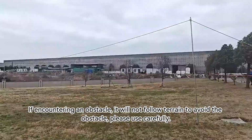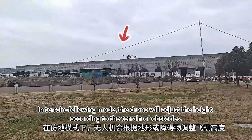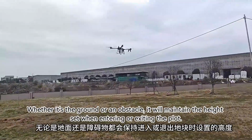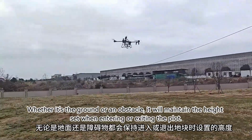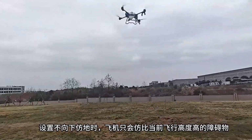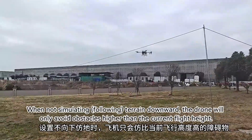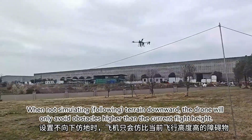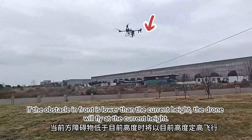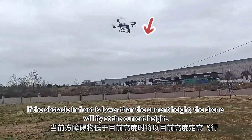Please use carefully. In terrain following mode, the drone will adjust the height according to the terrain or obstacles. Whether it's the ground or an obstacle, it will maintain the height set when entering or exiting the plot. When not simulating terrain following, the drone will only avoid obstacles higher than the current flight height. If the obstacle in front is lower than the current height, the drone will fly at the current height.